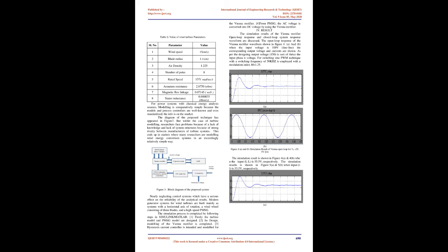D. Fuzzy logic controller. Fuzzy logic represents organizational laws in terms of linguistics, instead of mathematical equations. Some systems are too complicated to model correctly, even with complex mathematical equations, hence traditional methods in these systems are unreliable. However, the linguistic terms of fuzzy logic provide a feasible method to explain the operational characteristics of such a system. First, the multiple calculated crisp inputs must be mapped into a fuzzy membership function, which is named fuzzification.